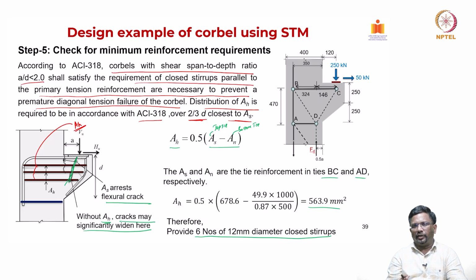So, this is again a detailing requirement. In reinforced concrete and pre-stressed concrete, detailing is very important. Otherwise, though you may assume struts and ties forming, if the reinforcement is not properly placed, it may lead to some cracking and then premature failure. So, we need to be careful.